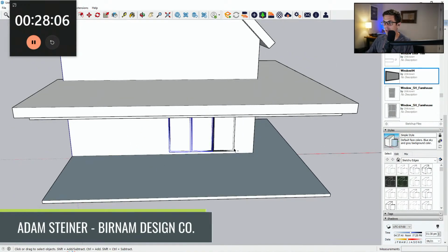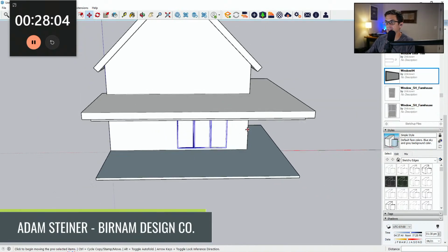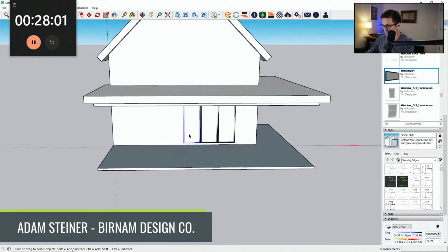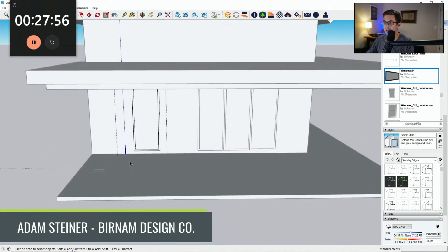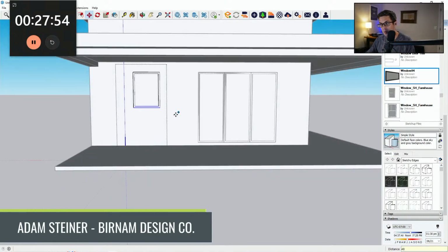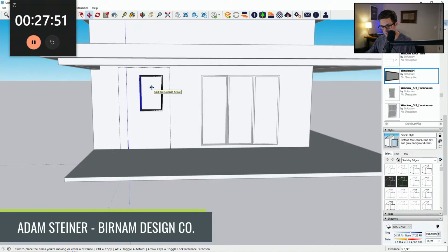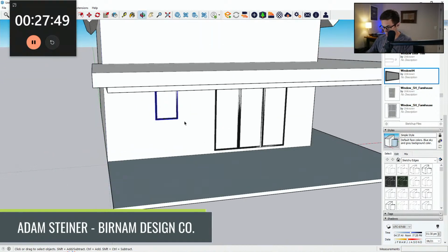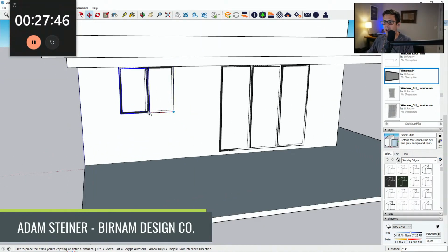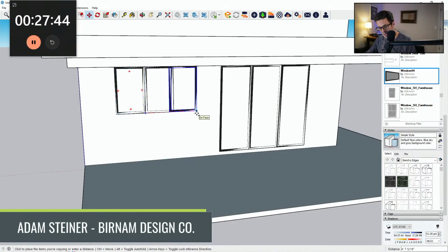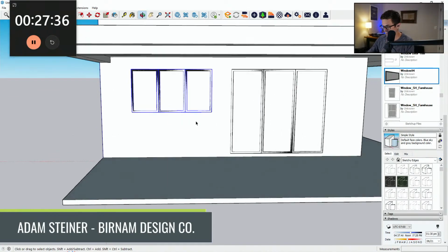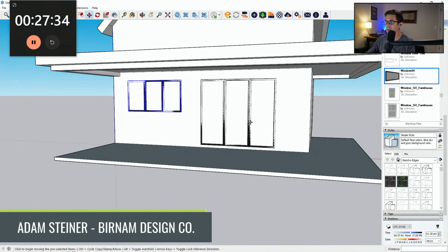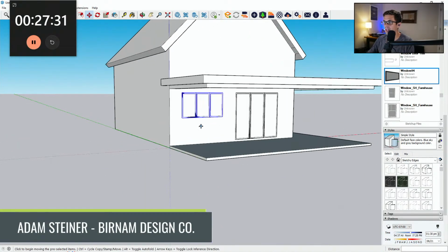Okay. Slide that slightly. Then we're also going to copy that over. I'm going to do some windows here. Make that unique. Bring it up 4 feet. Make it 6 inches narrower as well. So those are going to be a good bit off the floor. What I want with that, oops, is to make sure they're above that bench seat there, the back of the bench seat. But also carrying the same header height across, I think would be nice.